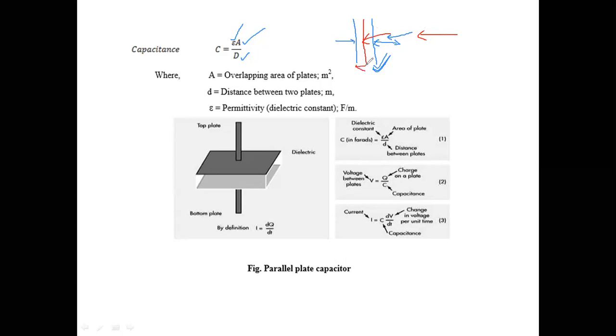The distance between the two plates is now decreased. So if distance decreases, what will happen? Capacitance increases. If I use the capacitor in the bridge circuit which I have shown earlier, then the output is induced. The output current is a measure of displacement.